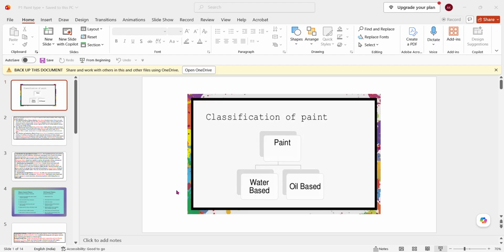Then bituminous paint, I have told you, is used where the atmosphere is very watery, there is a lot of moisture, and water is dripping. There you can use the bituminous paint, cold bituminous, which will be very useful when the climate is very moist and rusting will occur.